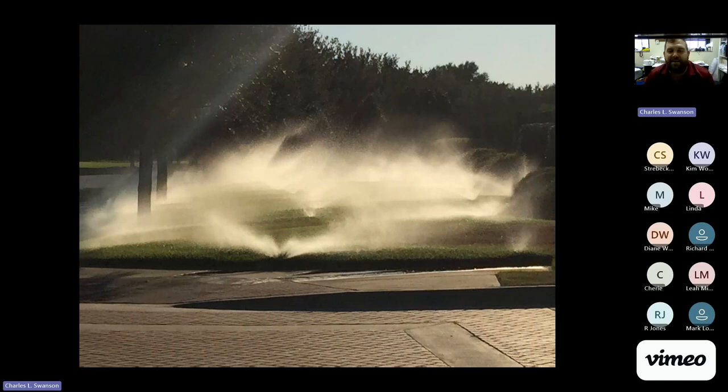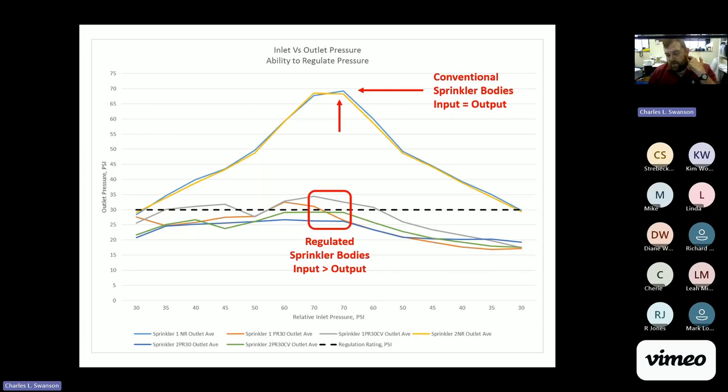Okay, here's an example of a landscape in a subdivision, actually in Bryan here, operating at high pressure. And what's the result of that? We have this very fine misting of water occurring, and that's producing very fine water droplets that are going to evaporate. They're going to blow away, and that water is not going to be applied uniformly to the landscape. So you could potentially have dry spots between your sprinklers because the water's not being thrown uniformly. So how can we overcome that? Well, we would use pressure regulation.